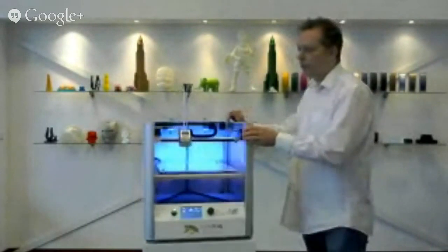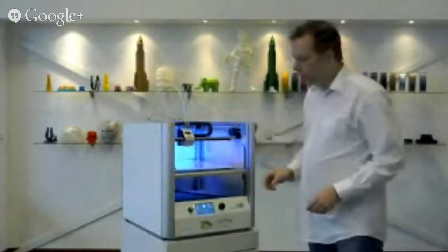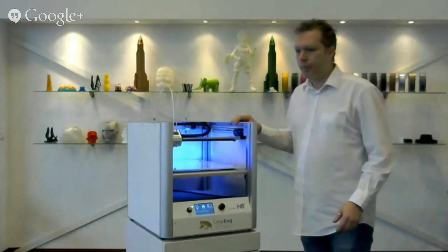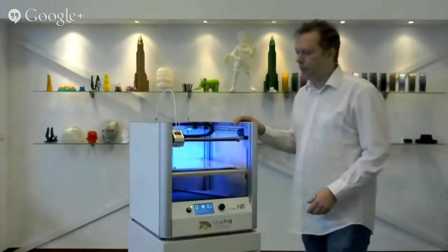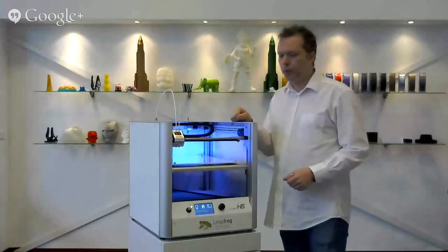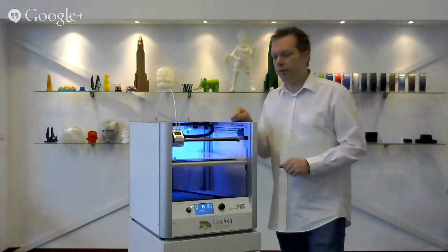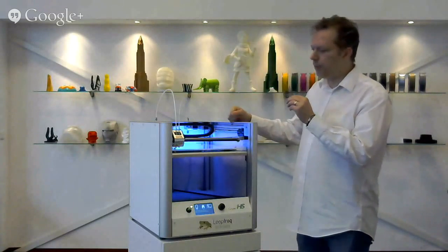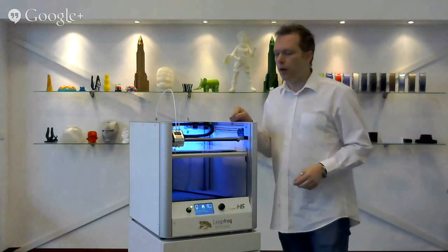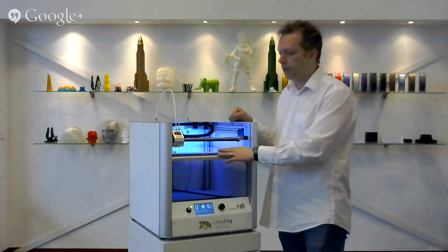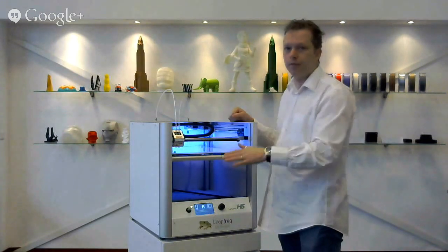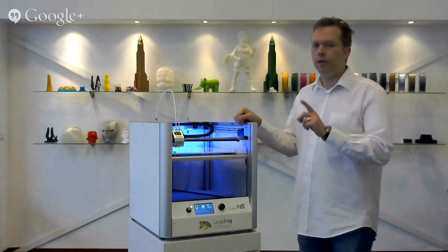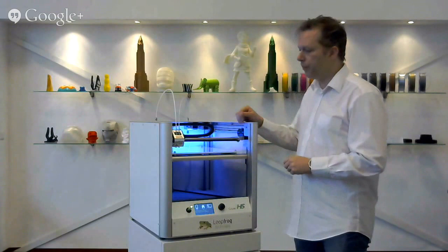With our standalone version, when you press home, the printer will start homing, and the bed will come up. What you will see is that the bed will drop down after that. This is specifically done because if the hot ends are going to heat up, it's not touching your build plate. So there's a gap between it. So it lowers the bed. But that makes calibrating without a PC really hard. There's a small trick I'm going to show you.